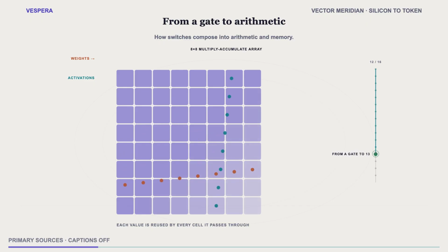And there's the whole hierarchy, sitting in the transistor budget. SRAM is fast and enormous per bit, so you get a little of it and you put it close. DRAM is dense and slower and lives on its own dies, so you get a lot of it and you put it further away. Nobody sat down and decided memory should come in tiers. The tiers fall out of the fact that the fast cell and the dense cell are different objects.